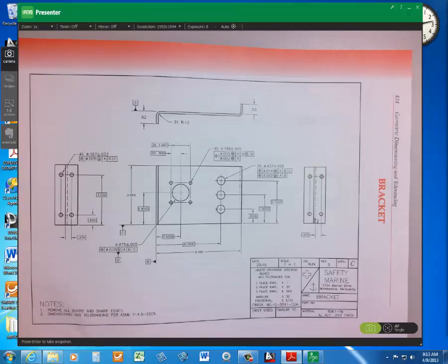So, composite positional tolerance has to be mentioned. Your upper part is at 10 thousandths MMC. The lower feature control frame specifies feature relating positional tolerance at 2 thousandths relative to A, and the feature relating zone is free to shift. The feature relating zone, 2 thousandths, is allowed to shift within the boundaries of the pattern locating zone. Feature axis must be within the boundaries of both zones. The axis. All right, next, 437.